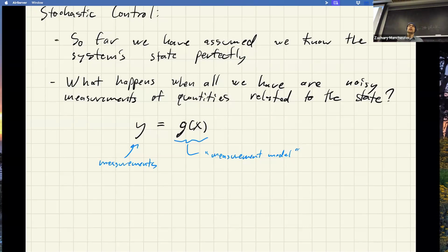And there's lots of other examples of this. The idea is we can always write down this forward measurement model that takes the state and maps it into a Y. It usually throws out information though, right? Y is usually strictly less informative than X as a general rule, and it's noisy. So we can't usually invert this thing directly. Given a Y, I can't usually take one Y and figure out my X. And so the game here that we're going to start getting into is how you do that backwards problem, how I take some Ys and reconstruct the X, and that's called state estimation.